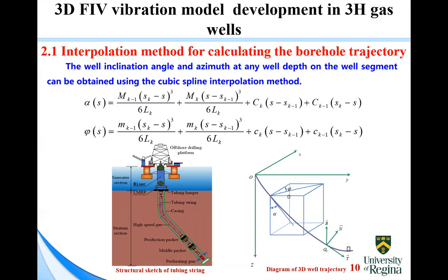Next, I will introduce the development of the three-dimensional flow-induced vibration model in high-yield gas wells. First, in the South China Sea and all over the world, HPHT gas wells increasingly use horizontal wells or deviated wells. So the well inclination angle and azimuth of the tubing string are more and more important to establish the model of the tubing string. So first, we use the cubic spline interpolation method to calculate the inclination angles and azimuths.